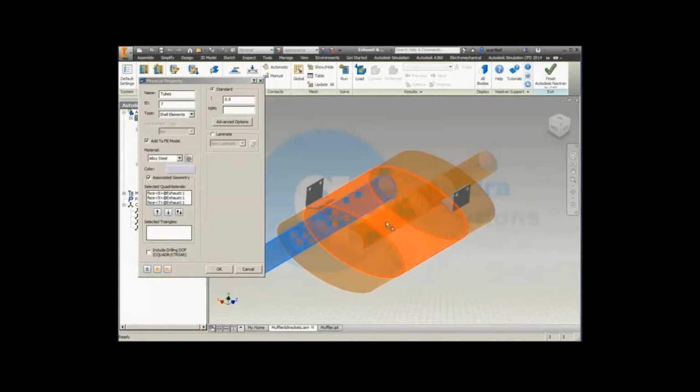So here within Inventor, just by hovering over the geometry, I'm just waiting there for the options to appear to be able to select that geometry that lies underneath the part that's blocking it effectively. So yeah, just working through this model, selecting all the parts within it and assigning this value to the geometry.